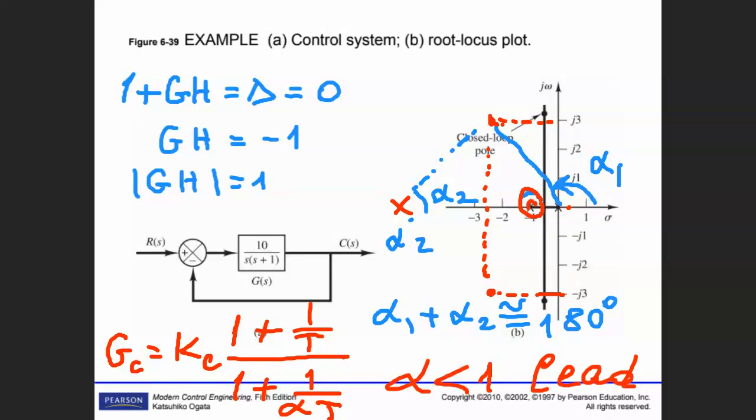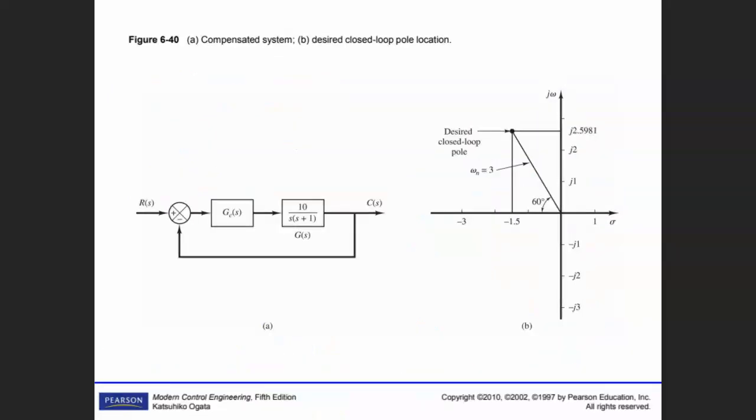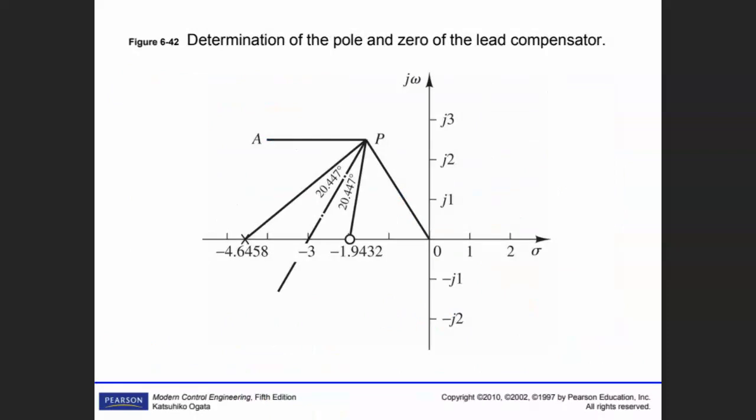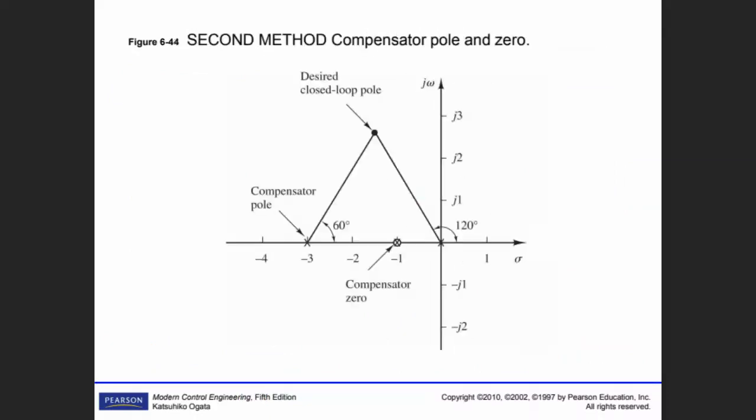When you do that, I've solved the problem, so I'm not going to repeat it. The second method I used, that's the one I used. So you can see that this is a selected, that is the selected point. You like it by controlling the angle here, zeta, real part, settling time, maximum overshoot. So if you are satisfied with those, then you say that this is my objective. Then you get rid of the original -1 on top of it. You put a 0 on top of it.